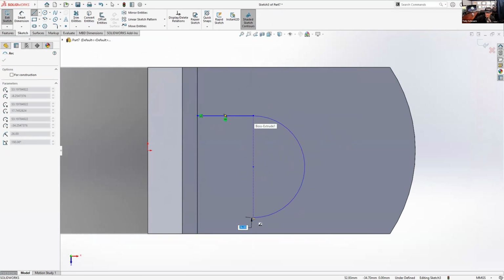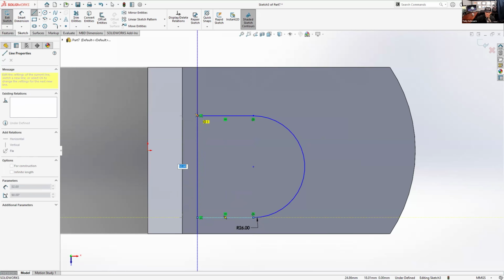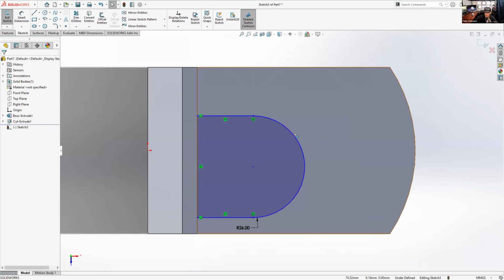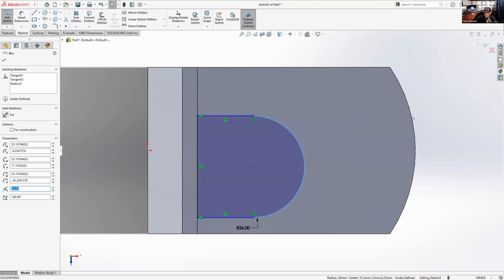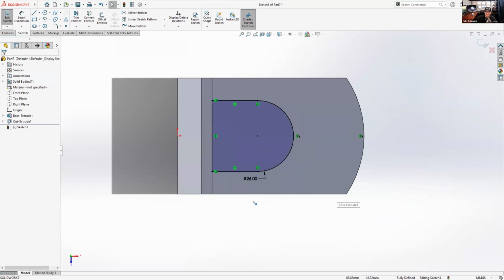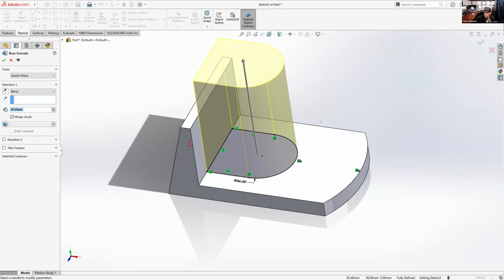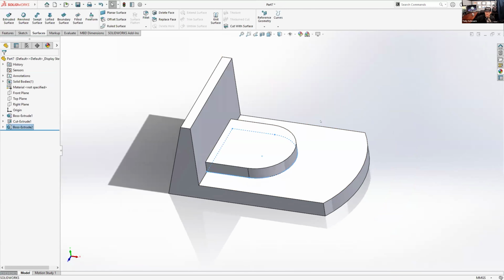And we'll get that exactly vertical there. So you see you're just referencing that relationship. Come back over to here. Close that sketch off. And I think the only thing we have to do is make that concentric, and that should go fully defined. So make those two concentric. Oh, yeah, that's what we like to see. And then S key extrude. What's the first field that's highlighted? It's the depth of that extrusion. So that depth is going to be 9 millimeters, 9, enter, enter. Now we're done with that feature, nice and fully defined.